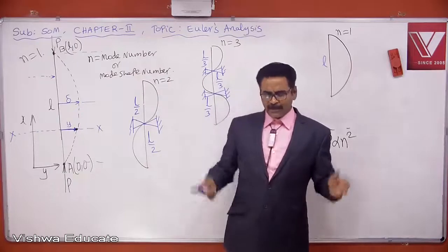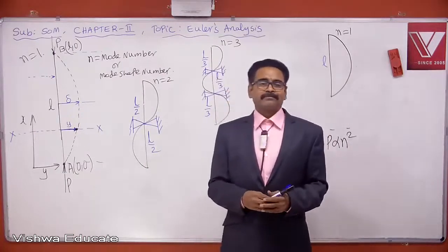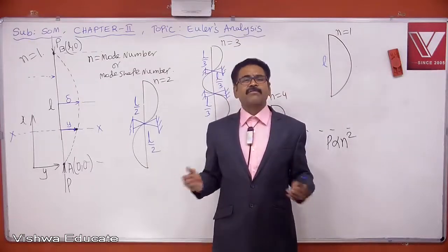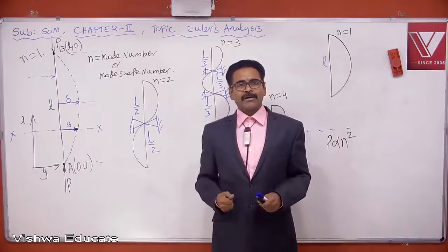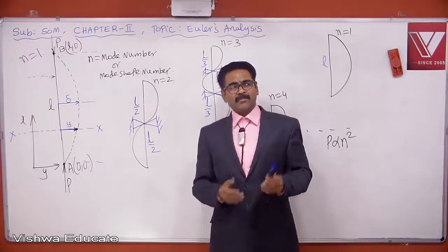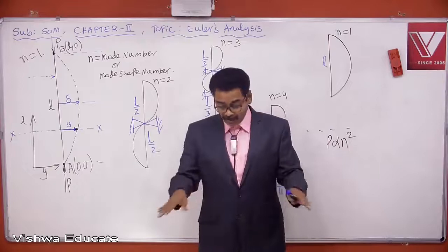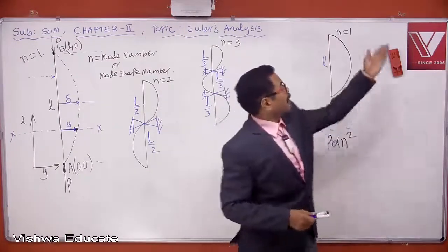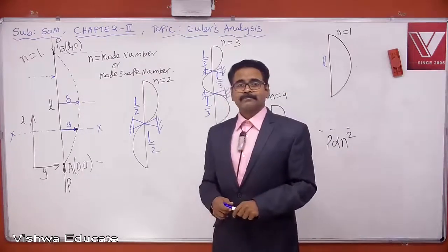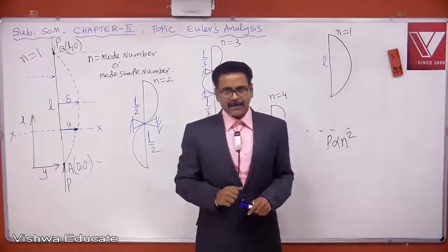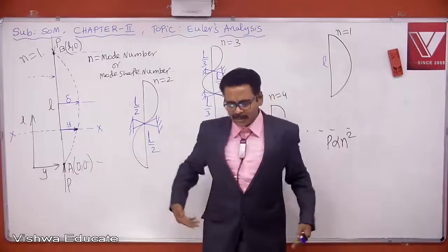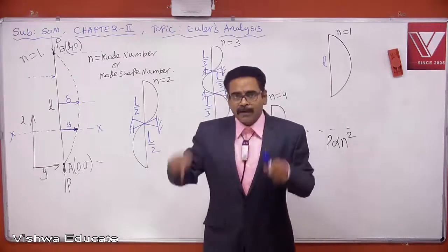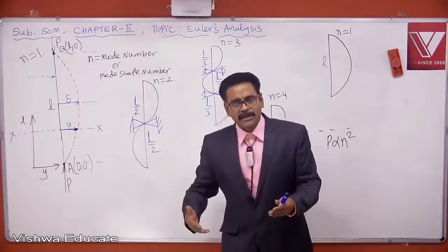For instance, a 5-story building is there. Currently, I am on the third floor. There is one column there. I am watching a column there. A column is there like this, maybe here. Now listen carefully. With respect to this column, what is this entire floor? When the column tries to buckle, this entire floor will restrict or assist.